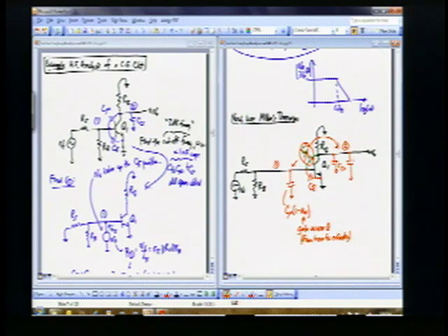Okay? Whatever that gain is, I'm going to take 1 minus that gain, and that's the new value for that capacitor. Okay, what is the gain across this? So I can write out this capacitor. It's just GM times RC, but it's minus GM times RC, because it's a common emitter. So that minus turns that into a plus. So that's what my gain becomes there. So the new capacitor that I stick right here becomes C mu times 1 plus GM times RC.